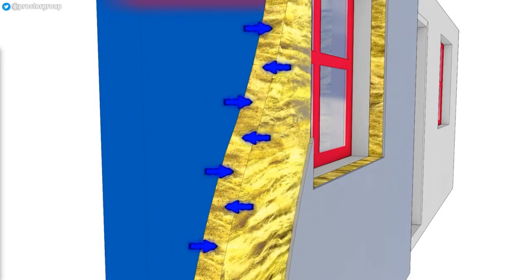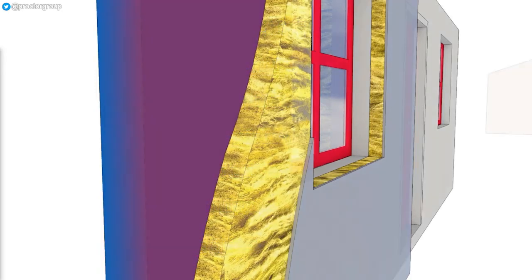Permeable insulation prevents moisture being trapped in the construction and does not disrupt the established balance of moisture flows within the building fabric to the same degree. However, traditional types of moisture vapour permeable insulation, such as mineral fibre, tend to be very bulky.